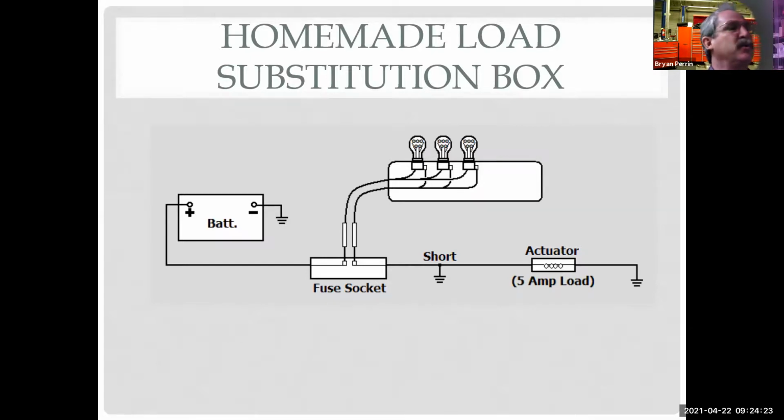The book talks about using a resettable circuit breaker. I don't like resettable circuit breakers for a couple of reasons. One is I'm resetting the circuit breaker so it's going to pulse. It's going to flow current, pop the circuit breaker, flow current, pop the circuit breaker. It's a little hard on the circuit breakers. It's hard on the wiring and the connectors, and I've actually melted wiring and connectors before I found the problem doing this. Because you remember, we're hitting the maximum. How many times are we going to hammer something against the maximum before something else in the circuit gets unhappy?